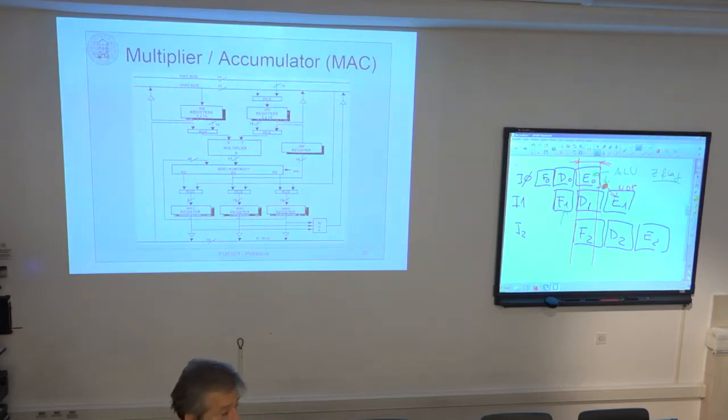These are 16 bits arguments, and they can be treated either as signed numbers or unsigned numbers. So as an additional flag of the assembly instruction for multiplication, you designate whether the first argument is signed or unsigned, whether the second argument is signed or unsigned. Based on this, it knows how to interpret this data, because of course it must know whether it is really an unsigned number or a signed number, the interpretation of the most significant bit in the register. Okay.